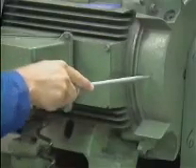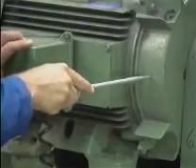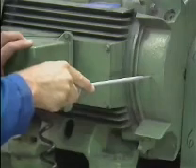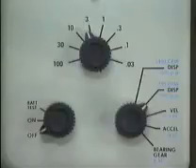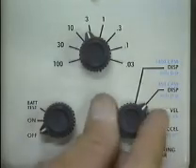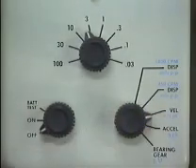To take a vibration measurement, you need to properly place the transducer on the component to be monitored. The next step is to use the function switch to select the vibration characteristic that is to be checked. If you're going to be taking overall vibration readings, it's usually best to start by selecting velocity, because it's a good general indicator of the severity of the vibration.